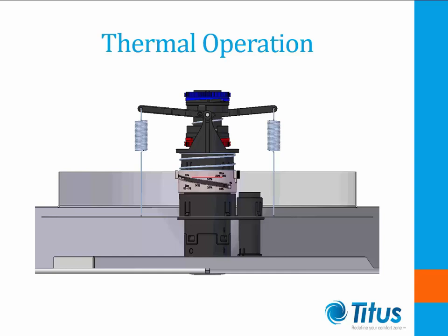Here we see the mechanism with an adjustable ring. The room temperature setting is adjusted for both heating and cooling modes with only two settings. First, the cooling temperature is set by adjusting the top ring, which is blue in this drawing, to the desired cooling temperature. Next, the offset between heating and cooling set point is set on the lower ring, red in this drawing. The offset can be up to 4 degrees in either direction.